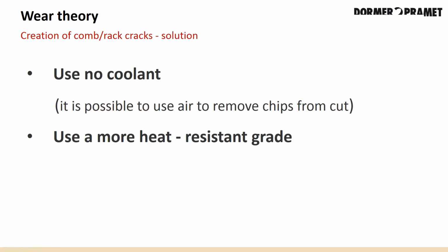So to diminish the effects, we can use no coolant and replace that with air to help remove the chips, or we can use a more heat-resistant grade.